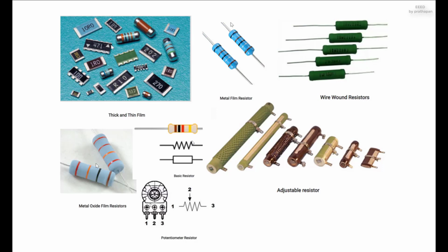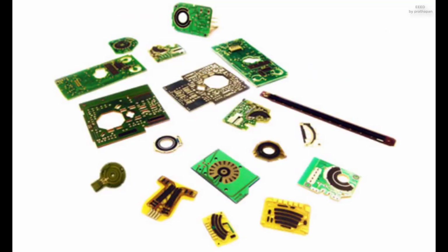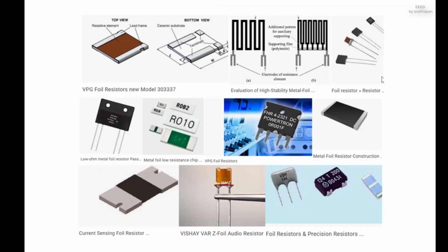Practical resistors as discrete components can be composed of various compounds and forms. Resistors are also implemented within integrated circuits. The electrical function of a resistor is specified by its resistance. Common commercial resistors are manufactured over a range of more than 9 orders of magnitude. The nominal value of the resistance falls within the manufacturing tolerance, indicated on the component.